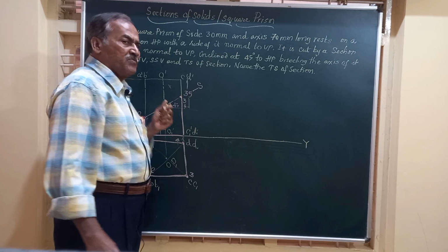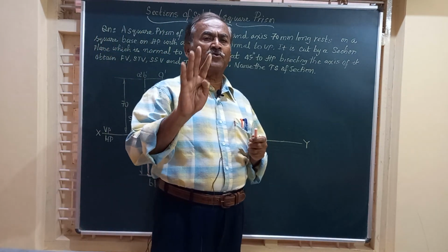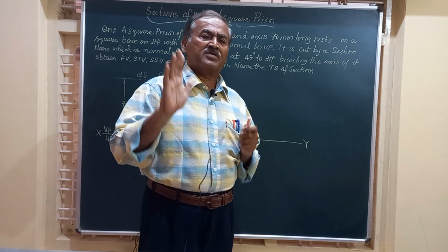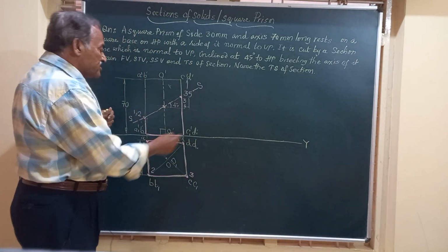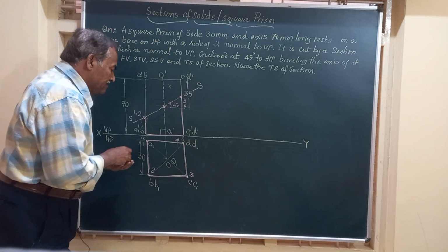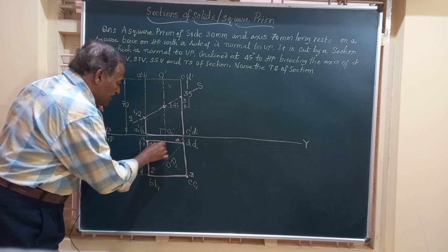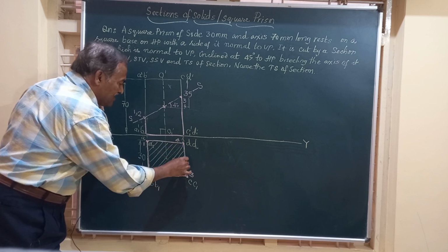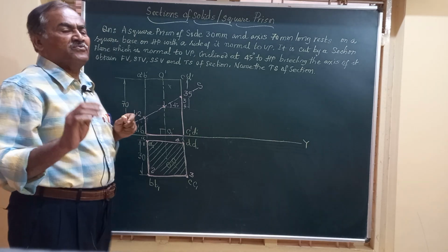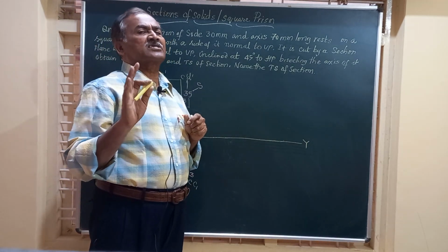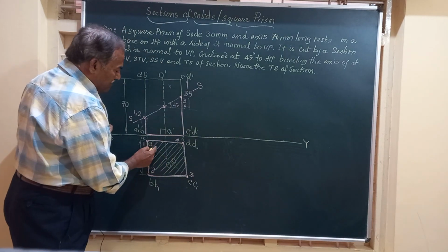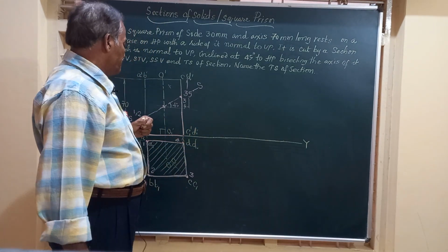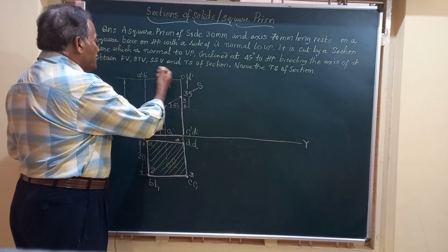we have got the top view, and after getting all those 4 points in the top view, and after joining them by straight lines, in case of all prisms and pyramids, we are going to section it or hatch it by lines equally spaced and parallel to each other. All these lines are generally inclined at an angle of 45 degrees to the horizontal. It is just a convention, and these gaps between the parallel lines should be around 2 millimeter when you make it in a drawing. Friends, we have the front view here.